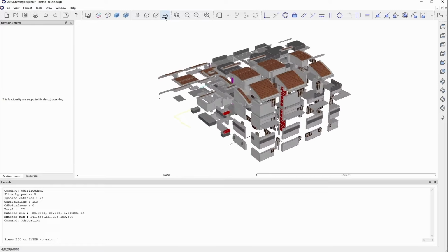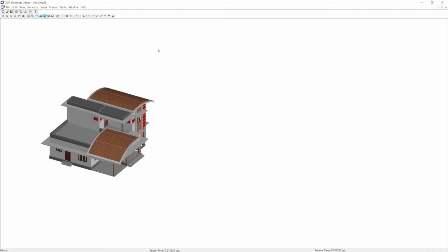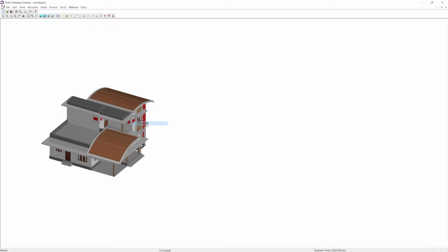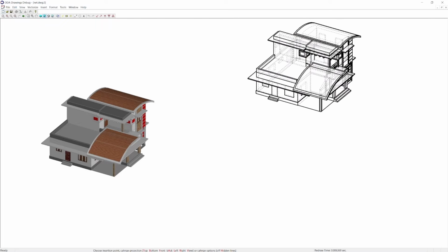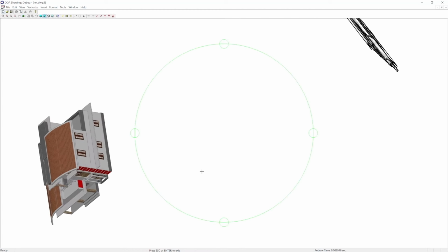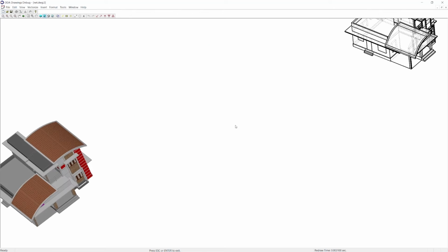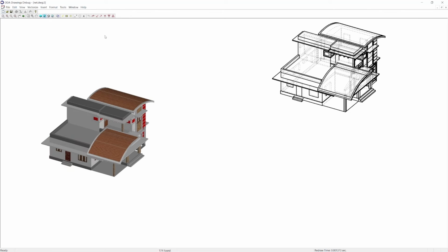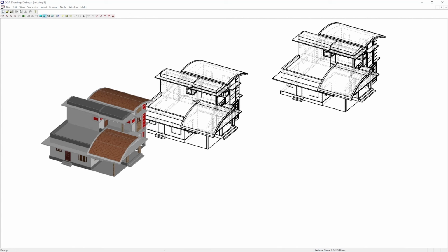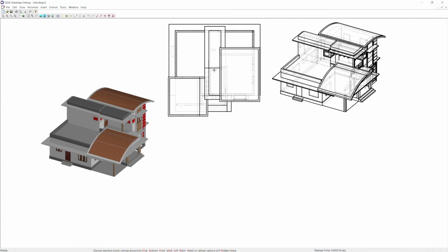Intermediate CAD workflows require not only creation of 3D from 2D. Flattened views combine tools to construct projections and sections. The core of this functionality is the ODDB section HLR helper class. It works with 3D solids, 3D surfaces, regions, sub-D meshes, and bodies, and allows us to select a section or a projection plane, set elements to construct a section or projection, create elements of a section or a projection, get visible edges, invisible edges, and section areas.